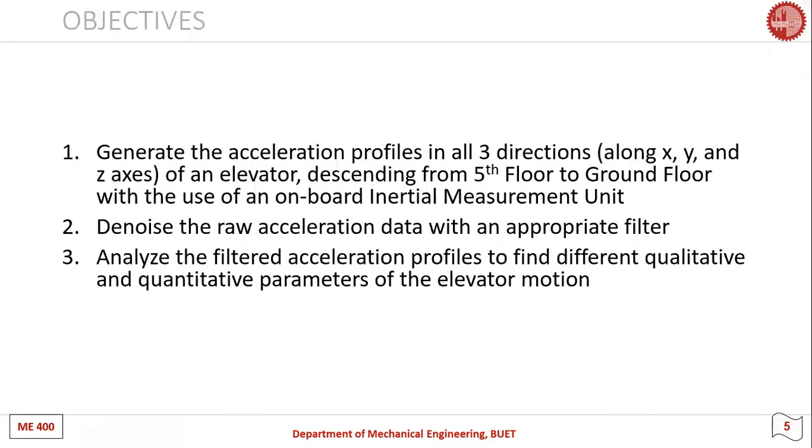Therefore, in this study, we have tried to use an inertial measurement unit to inspect the health of an elevator by generating the acceleration profiles in all three directions of an elevator which is descending from 5th floor to ground floor with the use of an onboard low-cost inertial measurement unit.